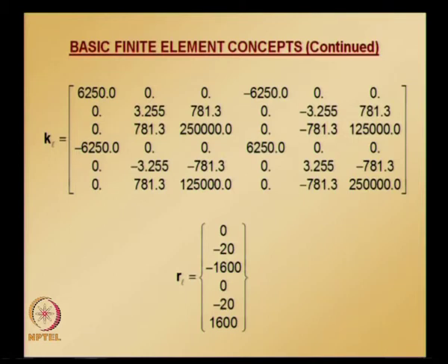Because of the boundary conditions, all the degrees of freedom at nodes 1 and 3 are 0. There is no need to assemble the corresponding rows and columns. Further, since the specified values are 0, the corresponding columns will not contribute anything either. So in the following global equations, only the terms associated with node 2 are written.